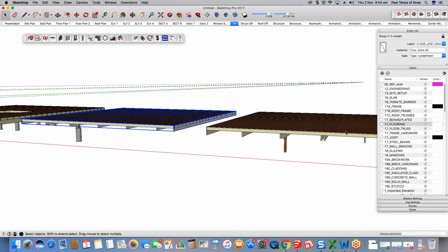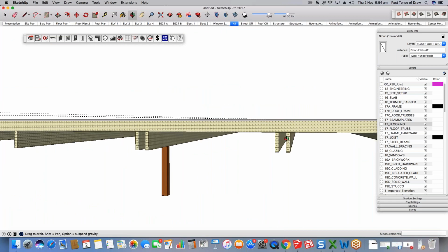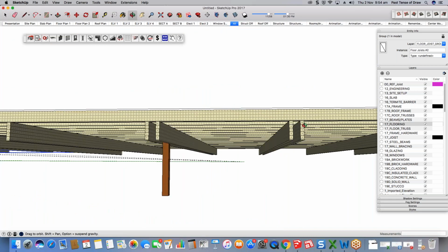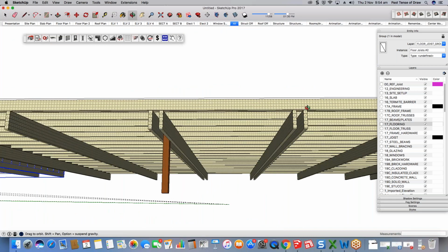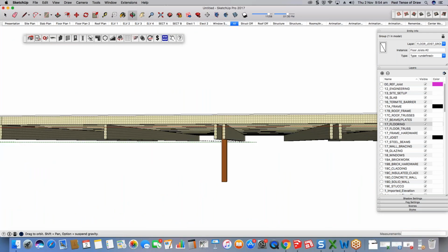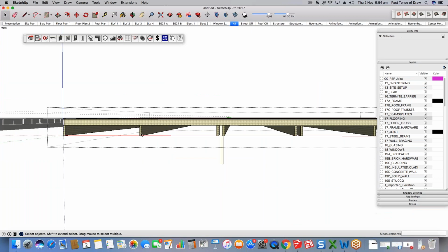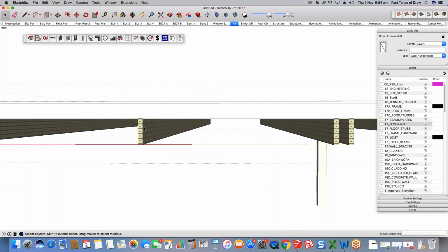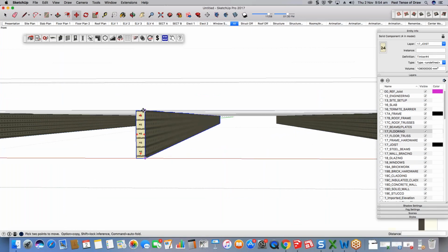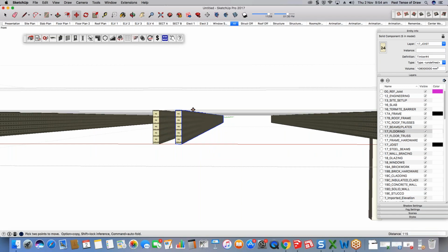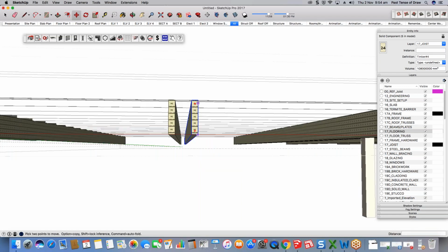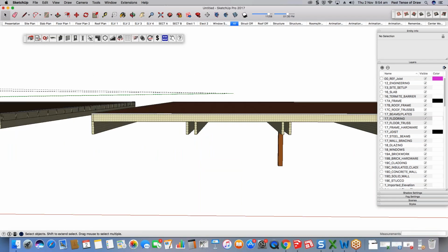Final one that I want to talk about is obviously beam to posts, so sides, so double bearers, etc. So the way that you're doing that, again, you're actually better off going, rather than doing the manual override by double clicking in and then grabbing the structure using the move tool and the copy tool and placing it. So you might know that it's 115 maybe. Rather than doing it that way, where again, if you do change your mind on any of the materials or structure, you'll lose all of your additional elements.